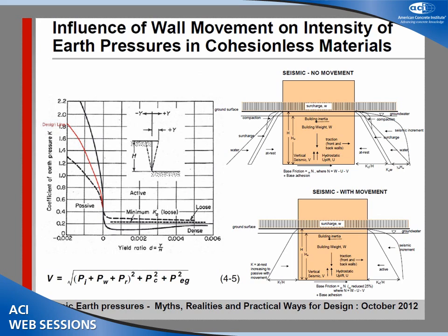So pretty much, if you are following the standard practice, once you obtain the different forces, let's say that you started assuming that your structure is not moving, you add the different forces, and apply equilibrium to your structure. Then if the resistance forces here at the base and on the sides and here in the back are larger than the driving forces, then pretty much you are done with the analysis.